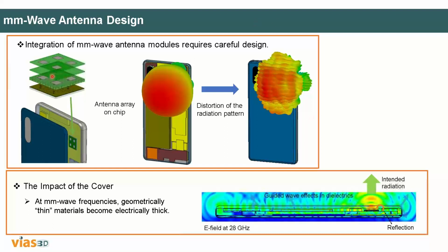So here what you are seeing is a multi-layer antenna structure, and this is an active antenna. This is the passive antenna, and these are the active elements here. Below that there will be a feed network, as you see, equipped with a phase shifter to form the beamforming.